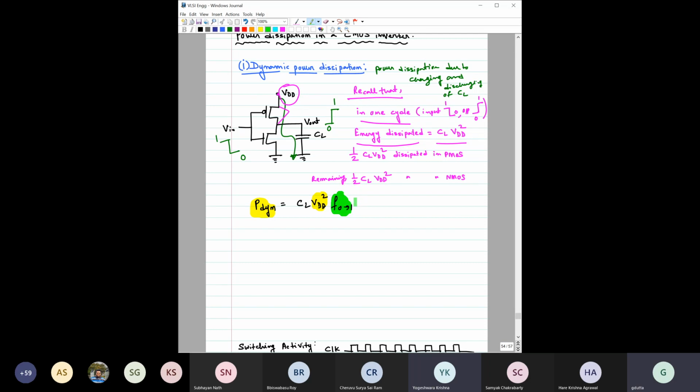So we will arrive at a situation where the total circuit performance would be limited by the dynamic power dissipation because of the very high clock frequency. So probably that will also restrict us, which is why we cannot further increase this clock frequency.